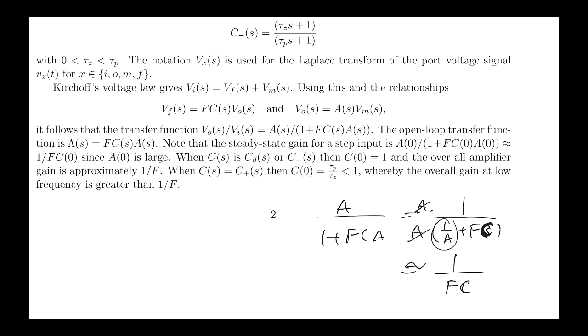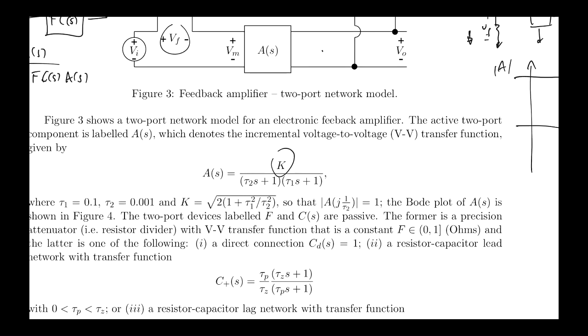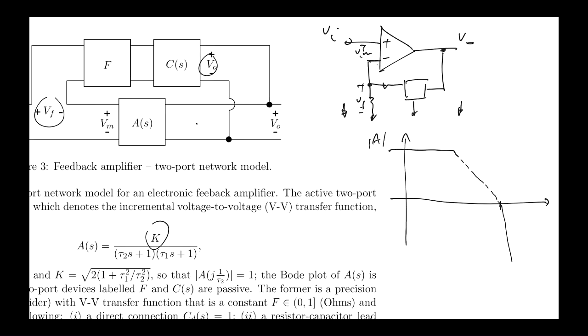And so what you achieve with a feedback amplifier like this, when you have very high gain through the op amp, is control over the closed loop gain, determined mainly by the feedback resistor divider network, which you can make very precise. It's very hard to build op amps with very precise gain characteristics. You might buy 2 op amps from the same manufacturer, and one will have a Bode plot that looks like this, and one will have it that looks like this.